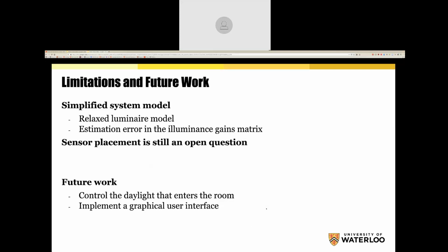Are we going from incandescent to CFL? How many people are occupying? If you have a room which is very rarely occupied and it's left on all the time, then of course it will be paid off itself very soon. But if it's a room which has no windows, then the daylight harvesting is not going to help you at all. So then you may as well just use a standard occupancy sensing PAR module. So it's kind of difficult to answer that question precisely.